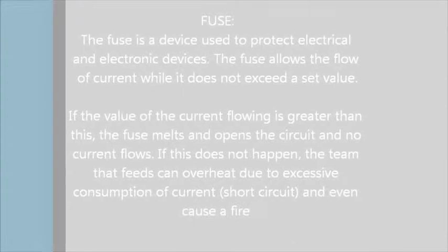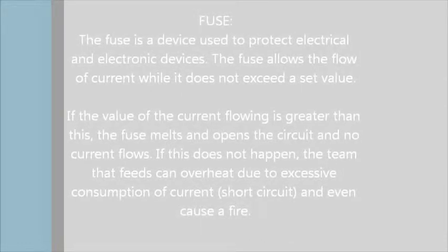Fuse. The fuse is a device used to protect electrical and electronic devices. The fuse allows the flow of the current while it does not exceed a set value. If the value of the current flowing is greater than this, the fuse melts and opens the circuit and no current flows. If this does not happen, the device can overheat due to excessive consumption of current and even cause a fire.